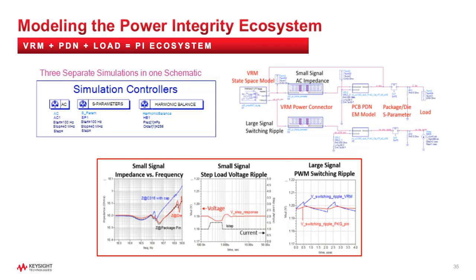The harmonic balance is very useful for DC-to-DC converter simulations where fast frequency domain simulations can be done at the harmonics of the switching frequency, and then the result converted back to the time domain for looking at the large signal switching transients or ripple.